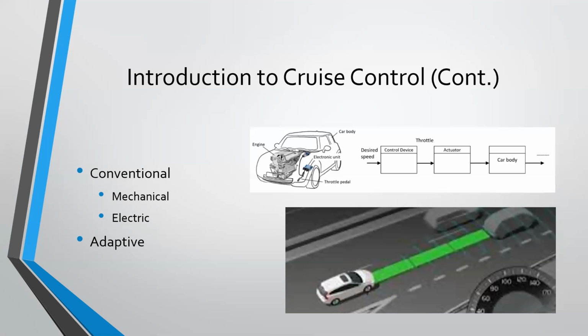When cruise control is activated and engaged to compensate for a difference in speed, the computer can easily adjust throttle position on the throttle body using an electric motor. Since there is no mechanical connection to the pedal, when the electric cruise control accelerates the vehicle based on dynamic changes, the desired input can be achieved quickly and more accurately due to the computer inputs.